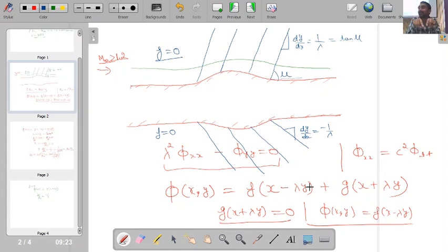Okay. So ultimately over here, we are not talking about the waves. When we are considering the linearized theory, we have not considered that a shock wave is forming here or there. But ultimately what we are considering is the solution of phi, and that solution of phi is coming in such a way that the isophi lines are actually coinciding with the Mach waves, if we just make the analogy. But here we are not talking about the waves. We have not said that we have any shock wave over here. Obviously physically there will be, but linearized theory is not accounting for the shock wave.